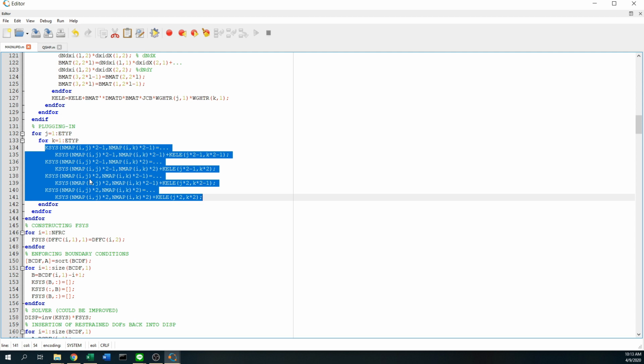If you want to use just the plate bending theory for the analysis, it is going to give you a conservative number anyway. So that could be done. Okay, you can use this one. Later on, we're gonna go for the 3D elasticity, but that is very expensive computation. So you might want to just stick with the cheaper one and make your design conservative. Anyway, right, we are done for today.